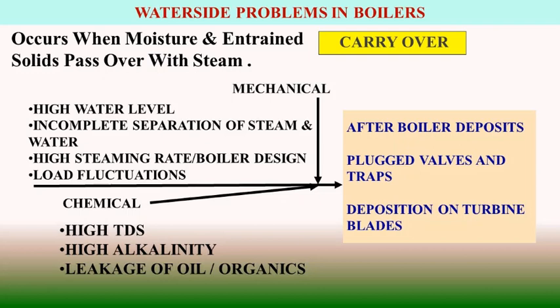By foaming we mean that when bubbles form on the boiler water surface and leave with the steam, that is called foaming. Foaming is caused by high TDS and high suspended solids and contaminants such as oil, grease, fats and certain organic compounds available within the feed water which is coming up to the drum. Oil in particular can cause major problems due to the saponification process, where it reacts with the caustic in the boiler water and forms soap-like compounds.